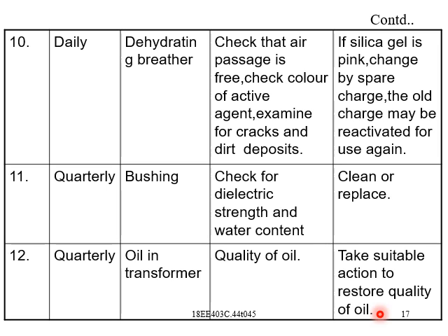Like we have seen in table 1, if any sludge or water content is deposited on the surface of the oil, we need to check that and remove it, and if the level of oil decreases, we can pour in more oil. If the oil gets totally damaged, you need to shut down the transformer, remove the entire oil and replace it with newer oil.